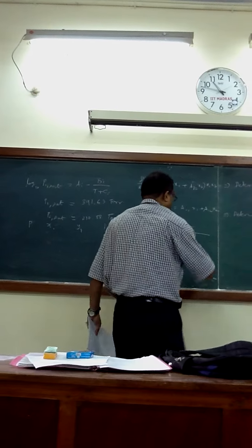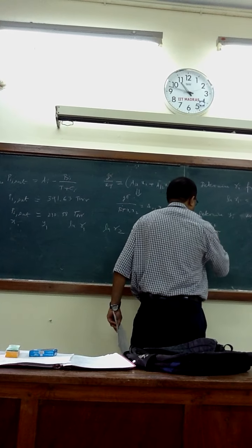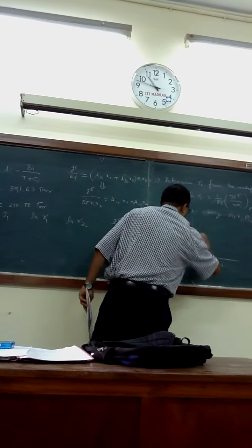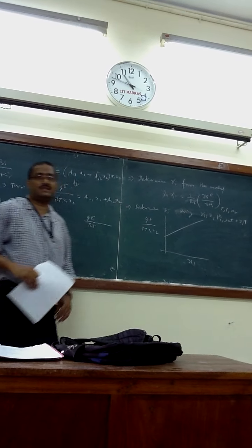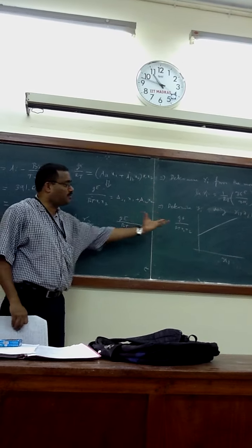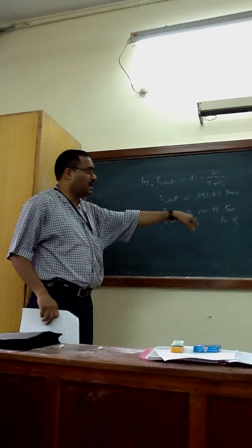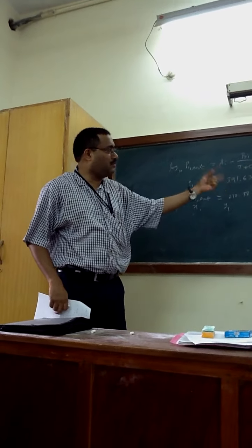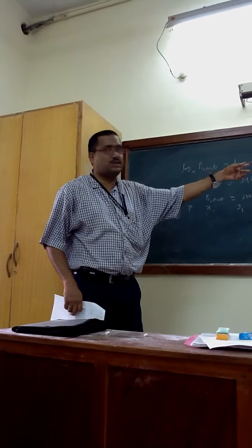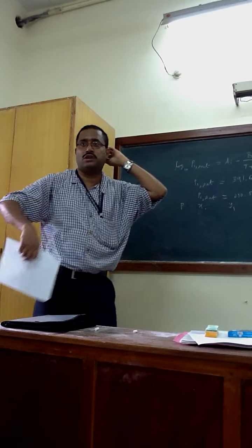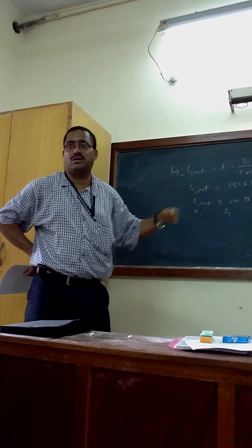So if you plot G^E/RT x1 x2 with respect to x1, it will behave like this. That's the way one can choose the model. Now let's see with your experimental data whether you can fit it. The slope and intercept will give you A21 and A12. You once asked me how to determine A21 and A12; that's the proper way.